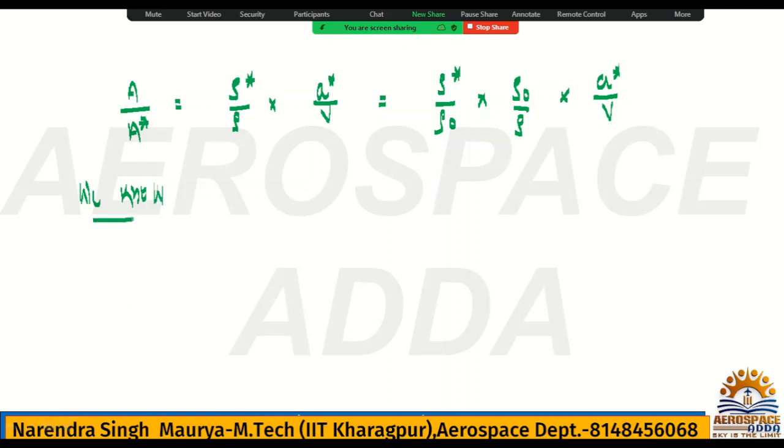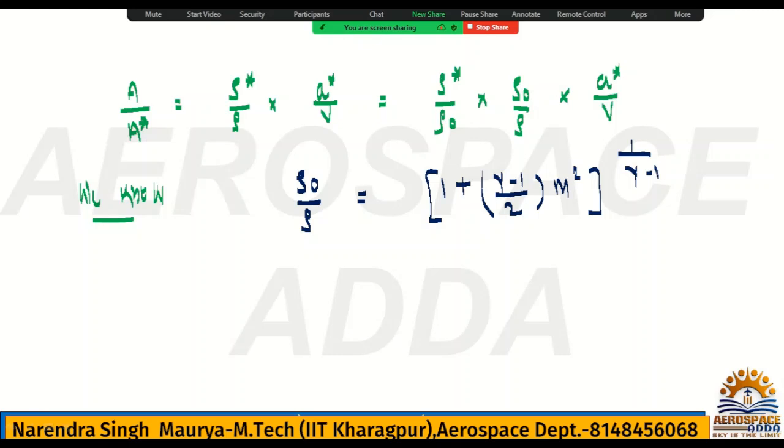Alright, what we know is that formula, simple. That formula we know, which is rho naught by rho. This is the isentropic relation: 1 plus gamma minus 1 by 2 M square, to the whole power 1 by gamma minus 1.